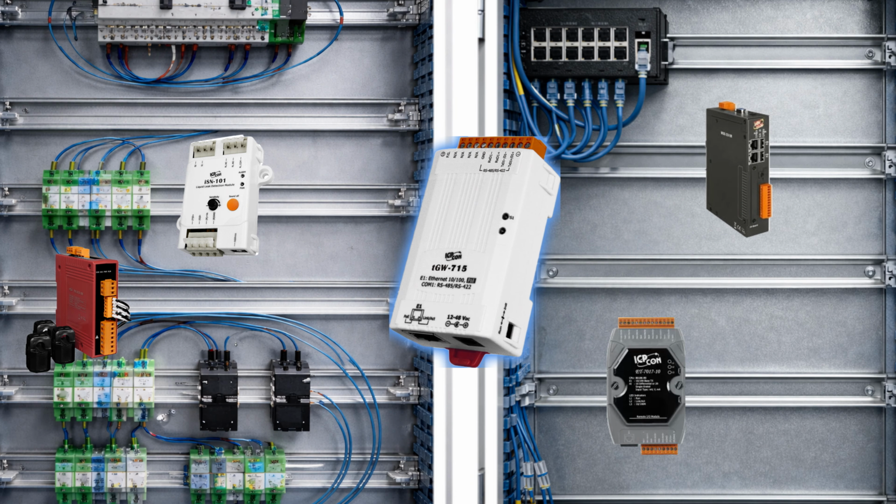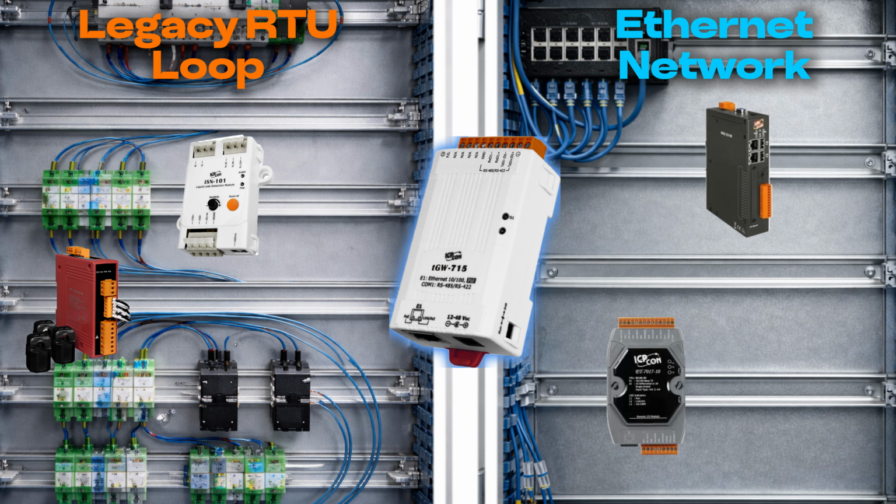A gateway sits between the legacy RTU loop and the Ethernet network. On one side, it speaks Modbus RTU to the sensors, and on the other side, it exposes the same data over Modbus TCP to your DCIM, SCADA, or monitoring platform. Everything stays where it is, your leak detection modules stay serial, your environmental sensors stay serial, but the facility gets full modern visibility. Gateways like the TGW series are designed exactly for this purpose. Take in serial data from the field, move it into Ethernet cleanly, and let the software layer treat everything as if it were native TCP.